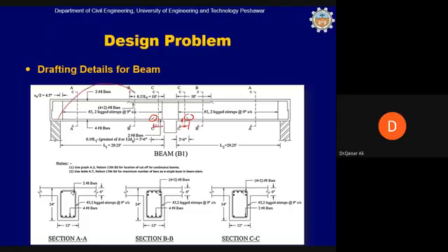The bending moment diagram will be like this. So you don't have a positive bending moment value in this location. You can do some curtailment here if you want. According to the ACI code, positive reinforcement cannot be curtailed more than 50%. So 2 bars must be carried from end to end. 2 interior bars can be curtailed. And the negative reinforcement can be 100% curtailed beyond this location. However, 2 bars are necessary to hold these stirrups. The stirrups have been provided at the rate of 9 inch center to center.